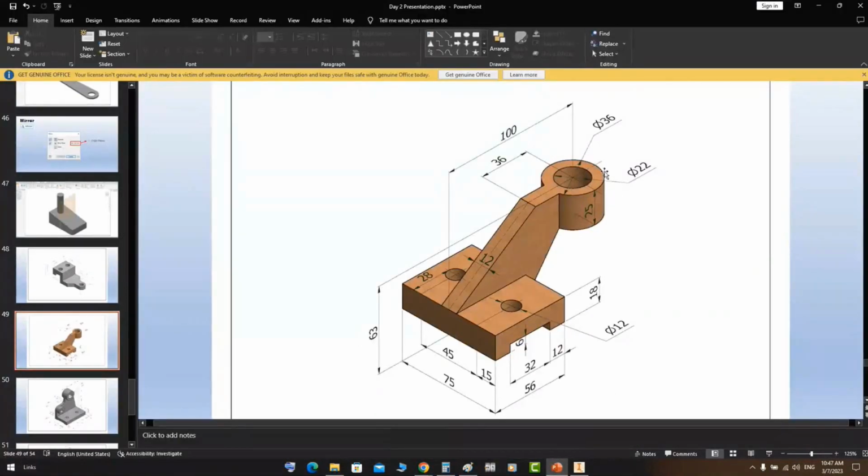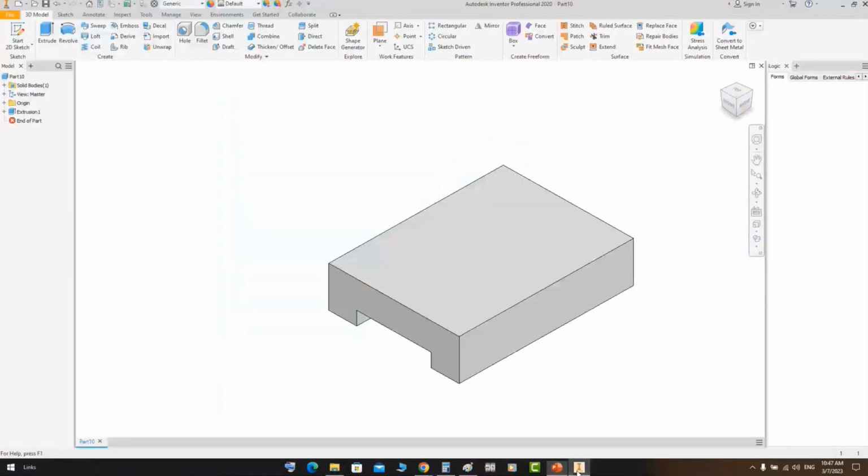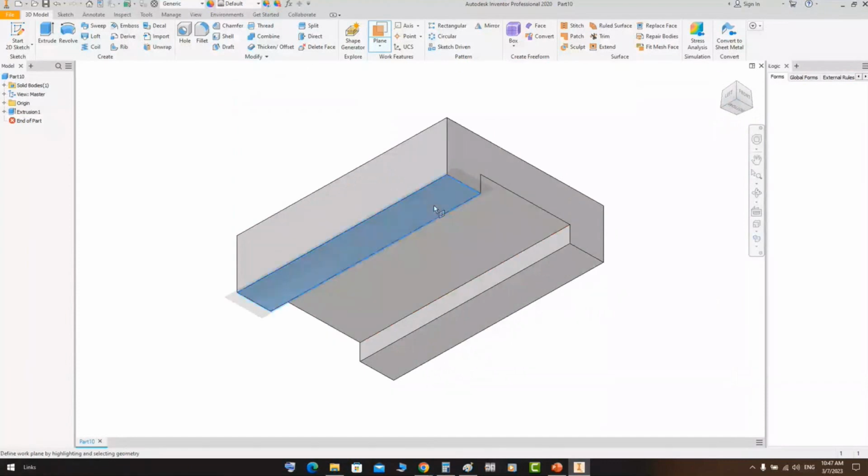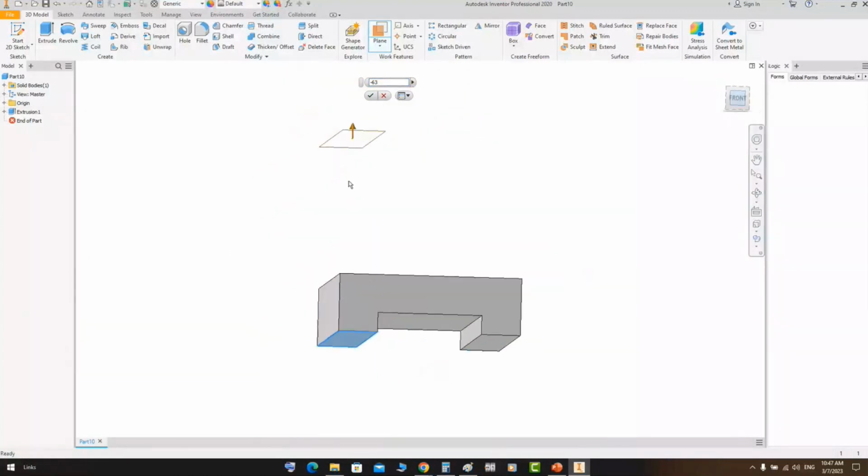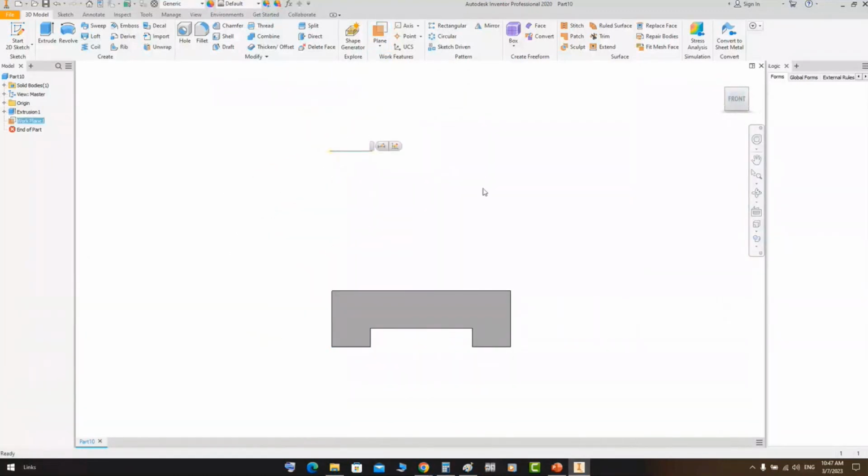Now we have another cylindrical shape above here. This cylindrical shape from bottom to top is 63 millimeters. So from the top level of this circle to the bottom level, it's 63. So let's make a work plane. Select a work plane, and from here, select that surface and move up here and make 63 millimeters spacing with a negative value. So we will get this plane.